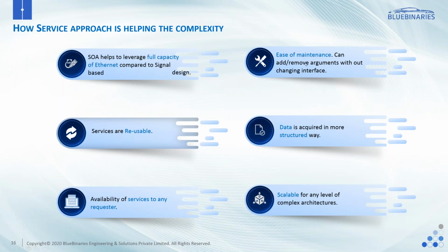It is easy to maintain, as I said: you can add or remove arguments without changing the interface. You can acquire data in a more structured way. In the signal-based design, you receive independent signals, and then you need to structure them to get meaningful information. But in a service-oriented design, you get the payload in a well-structured manner, and you can process it as it is. And as I said, it's scalable, so you can increase or decrease the arguments, or you can add a complex service where a service itself can have multiple services inside.